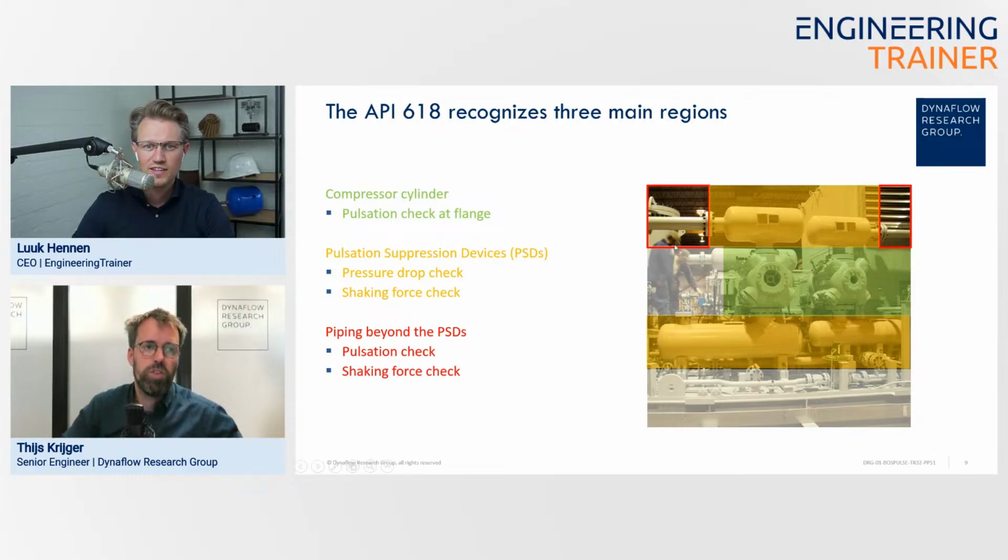So in design approach 2, the guide they use there is that the mechanical natural frequency of the piping system needs to be 2 times plus 20% above the running speed of your compressor.